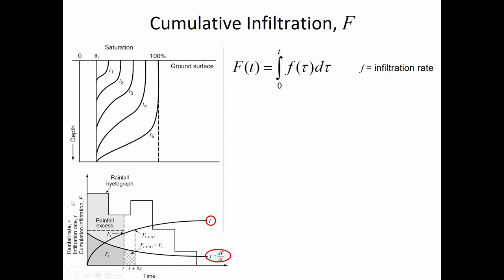So look at the rainfall. Initially there was a pretty high rainfall intensity, then the rainfall decreased a little bit, but in each of these cases, the rate of rainfall was greater than the infiltration rate. That means there's going to be ponding at the surface. There's more water at the surface than can be absorbed by the soil. The Green-Ampt simplification requires that. It'll be even less accurate than usual if we don't have ponding at the surface. So that's one of the things I have to tell you: the hydrograph of rainfall needs to be above the infiltration curve for us to have any hope of accuracy.